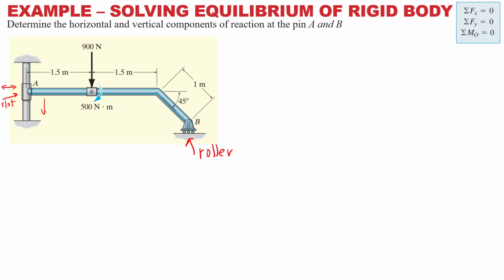So, okay. Let's label our free body diagram. Number 1, the free body diagram must be correct. If the free body diagram is not correct, everything is finished. So, this one is one direction only. It cannot go down. So, the reaction force here, B, what do we call it? BY. This one has a moment. Extra moment, 500 Newton meter. This is the direction of the moment. The moment is negative. You can put a negative sign so that you remember this is negative.